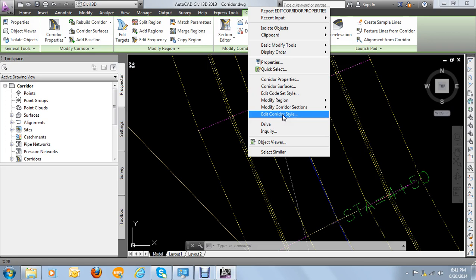There may be just a few critical points where you have to change a lane. Otherwise the road section is the same up to a certain limit. After a certain station, you have to change the assembly, and changing the assembly means you have to specify at what station. Is it understood? Any question?